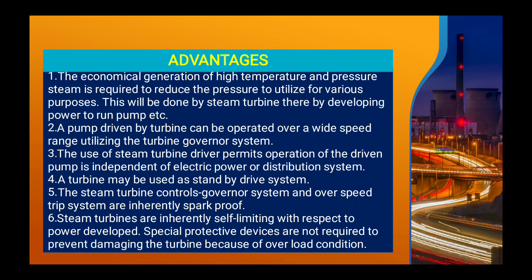The use of a steam turbine driver permits operation of the driven pump independent of the electrical power or distribution system. So even if no electrical power is used, we can control the speed of the pump by the help of the turbine. There is no motor required for that operation, and a turbine may be used as a standby drive system.